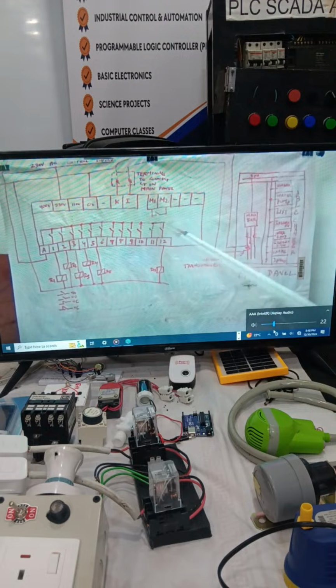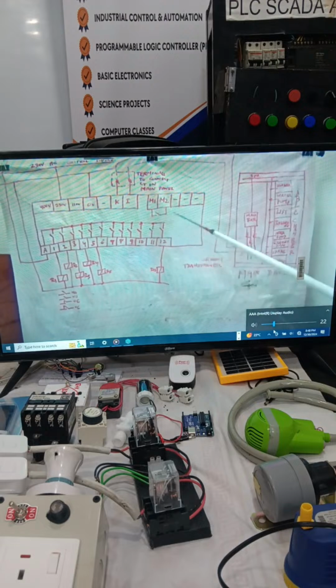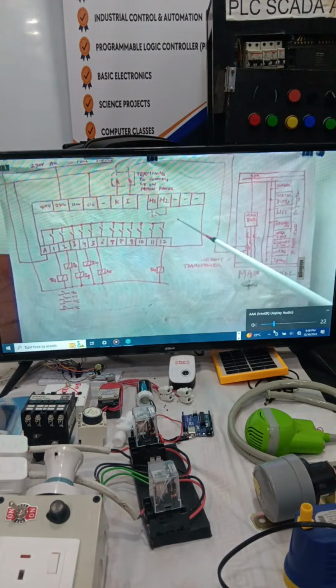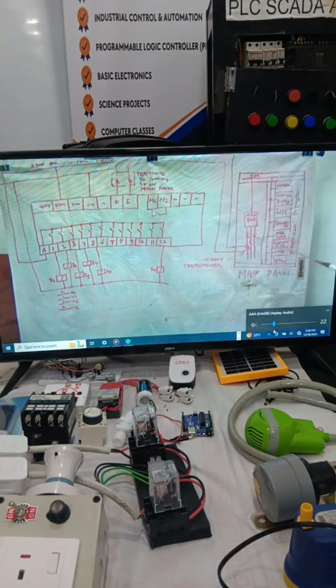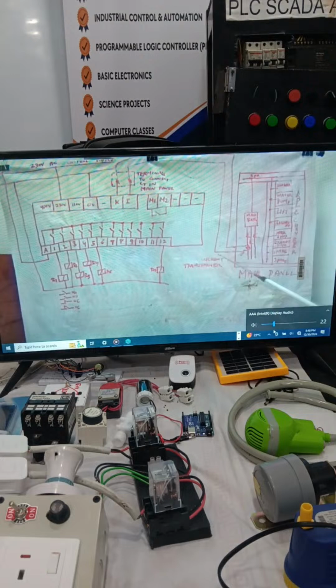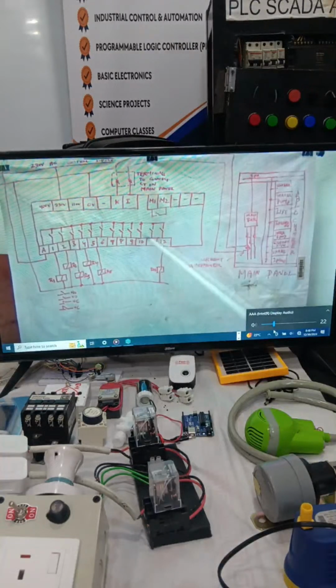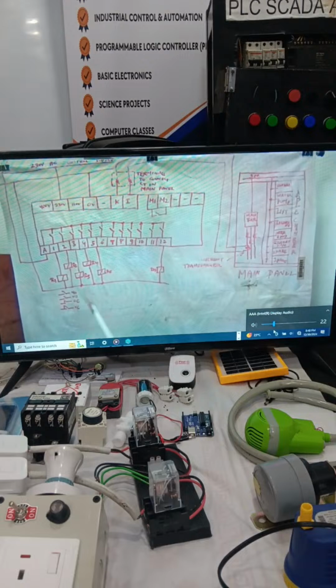So this is a comparator. Inside it we have to put the target power factor, 0.98 or 0.97 or 0.96, and the comparator will compare the nature of the power factor of the system, and it will give a signal to close these contacts 1 to 12. So depending upon how many kVARs are required, these contacts are closed or open.